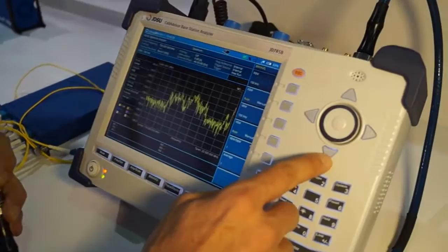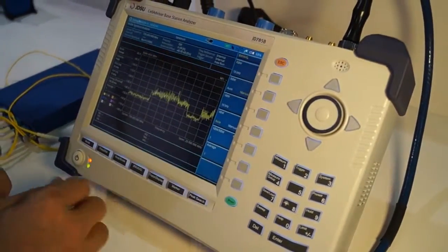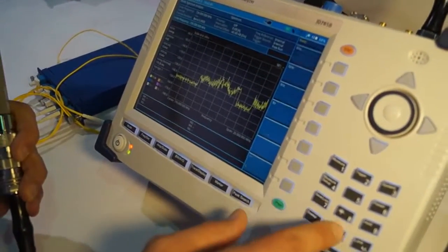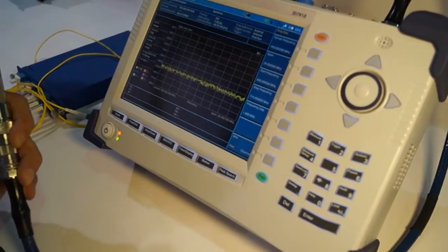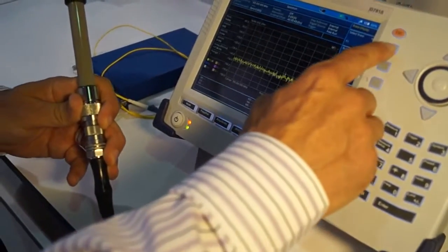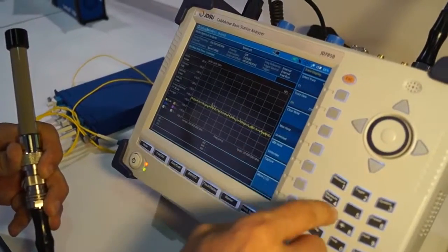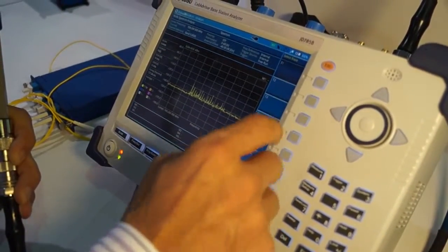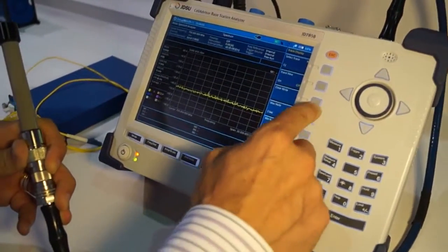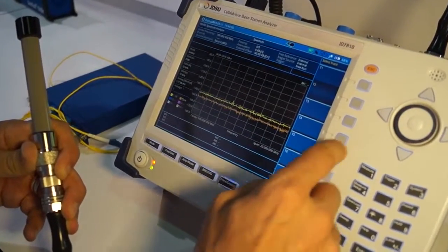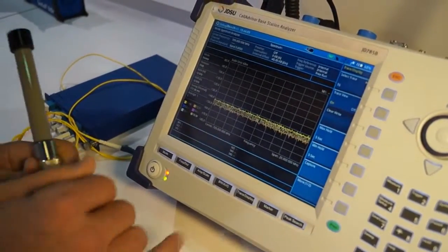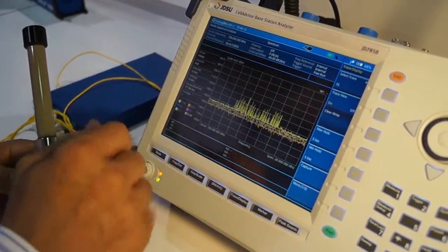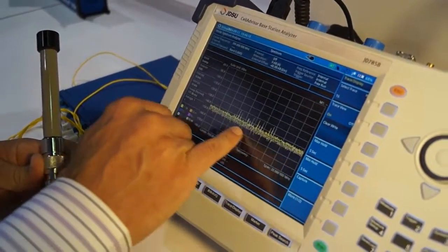And here I'm just going to make a few adjustments and show how people actually are truly looking for interference. So as an example, this is a signal from AT&T and the uplink is on 709 megahertz. So here we're going to be looking for any type of traffic that might be happening. I'm going to be enabling a few traces here, and what we have is just the activity that is happening with the signal. Every time that we have an interference, that's activity from mobiles that we're capturing, although it seems that right now on these traces we see that there's no interference.